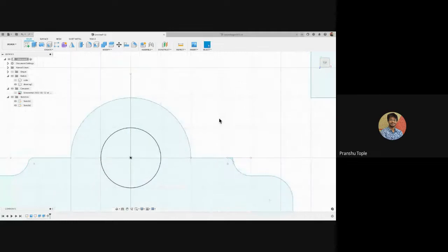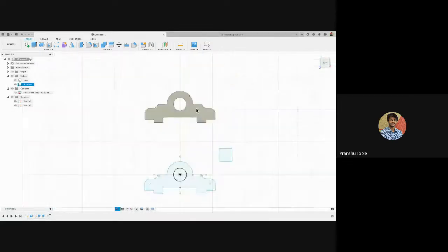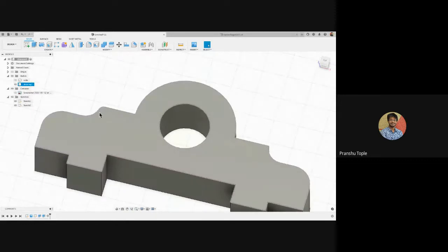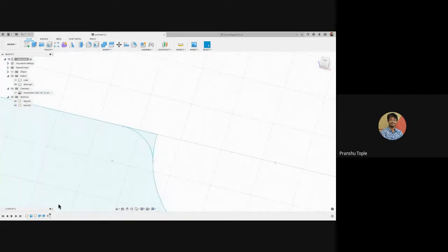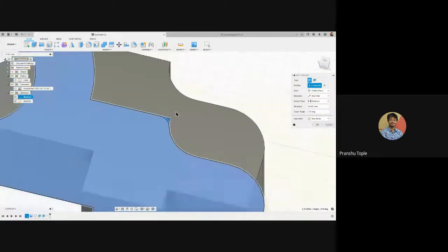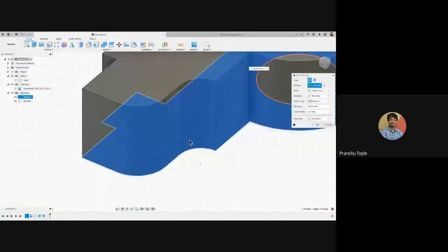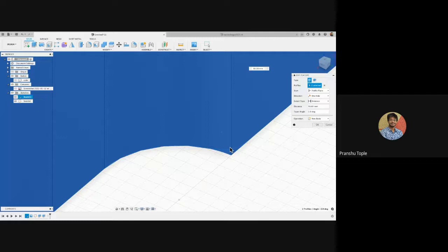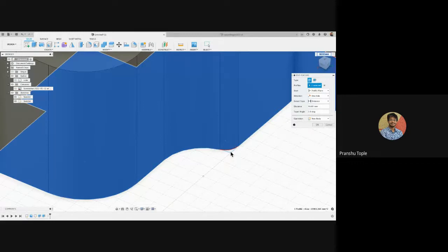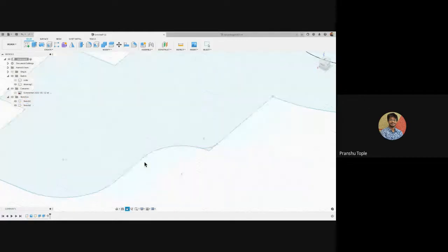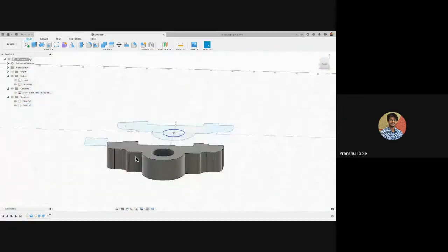Now if we come to this part, we can see this fillet has been generated over here, but here it is not generated just because we still have this small part. So what did we do? While extrusion over here, I can edit the feature. How can I edit it? While editing, it says you selected the complete structure. So I will press Control and say okay, while extrusion, don't select this small portion, and I will leave my control. Press OK. Now if I zoom out, I see all the edges over here are curved.